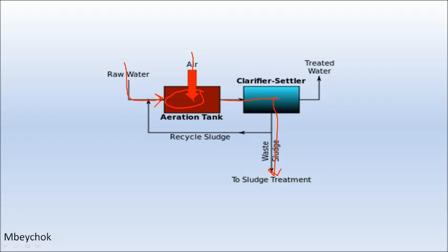anaerobic digester. There's another option here, which is that instead of just discarding that material, it can actually get recycled, and it can be used to inoculate the next batch of primary effluent that's about to enter the secondary treatment process. And the more microbially diverse these flocs are, the more unique different types of metabolism are represented in the activated sludge tank, and the more unwanted chemicals and different types of microorganisms and organic nutrients that can be filtered out of the water.